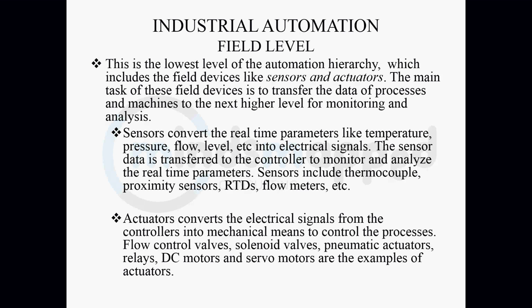So if it's a valve, in the example that we have been using, if the hot water temperature sensed by the temperature sensor is going above the acceptable range, then the controller will make a decision to close down the valve.